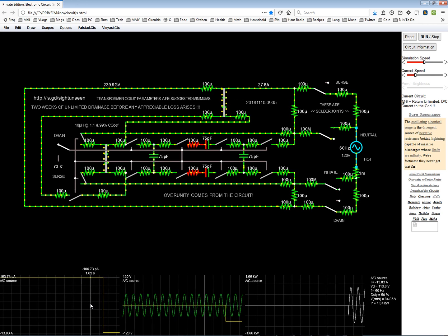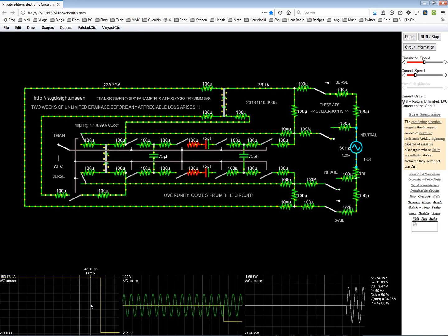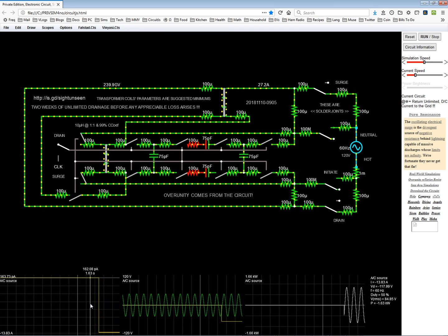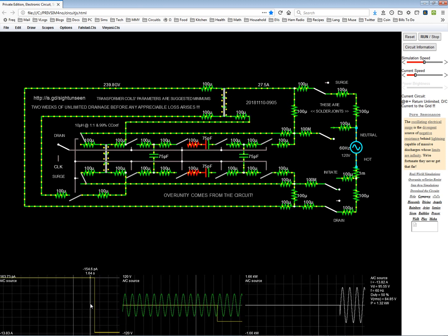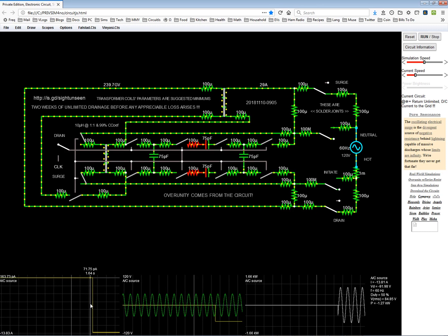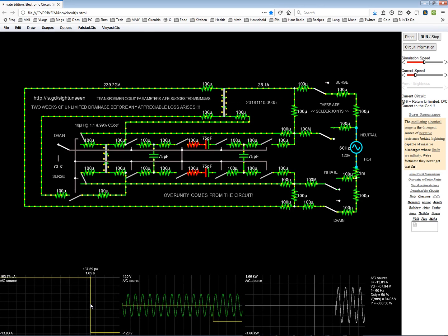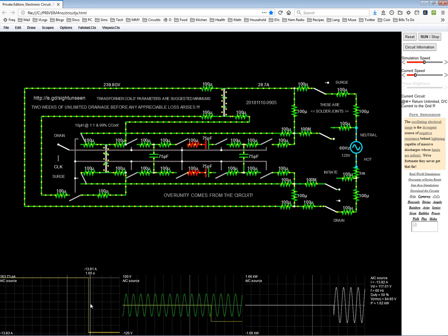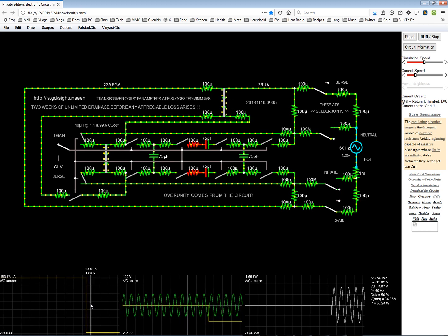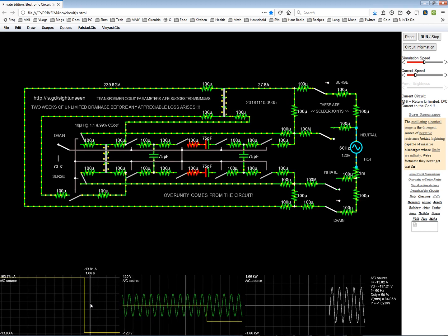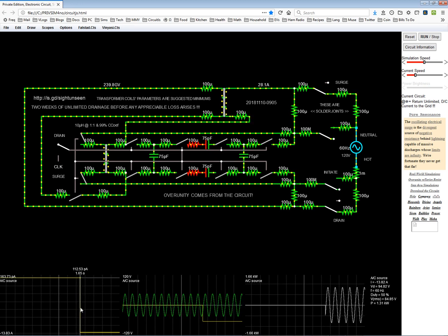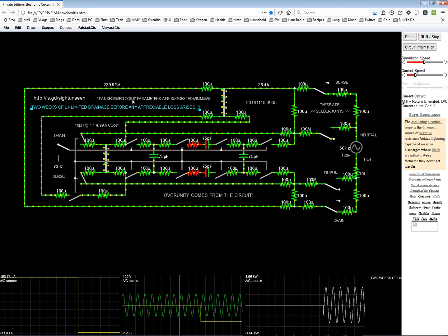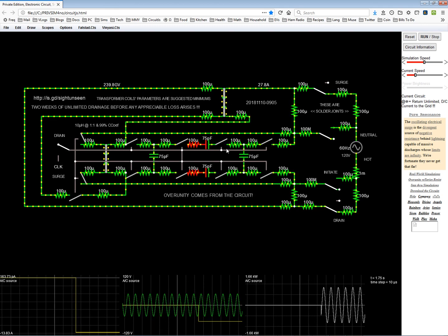On a branch circuit, say if you pick one outlet in your home, that branch circuit has a 20 amp breaker, but the rating of the wire is 15 amps maximum. 20 is the safety limit, but 15 is our end safety limit, so that's why I try to keep it under 15 amps, and that's why I went to a lot of trouble to fine tune this so that I could get to this.